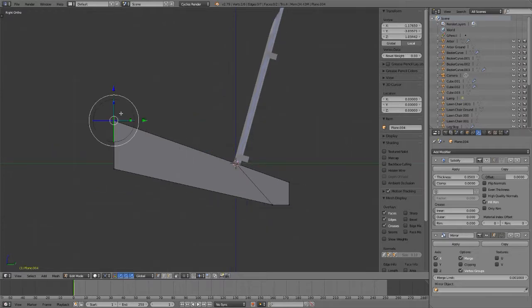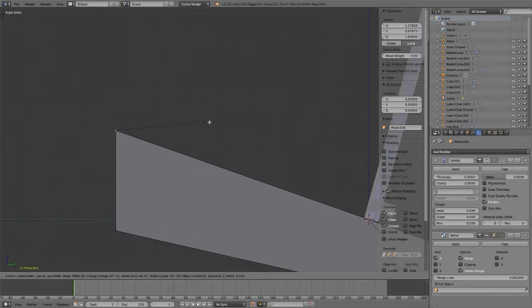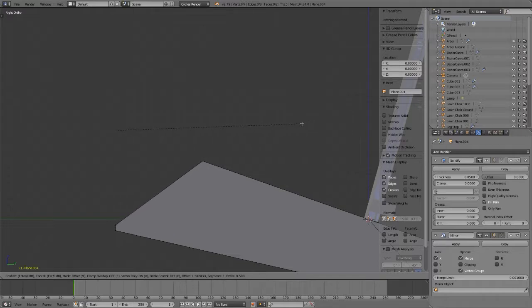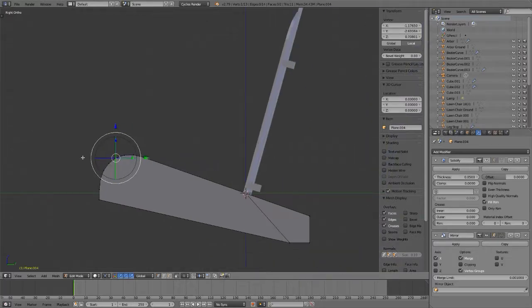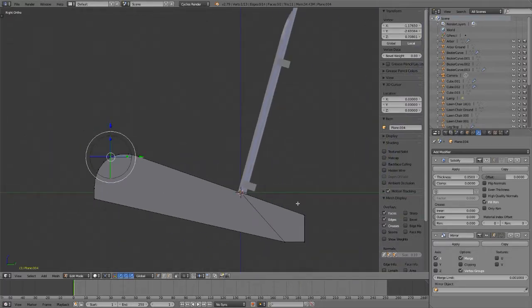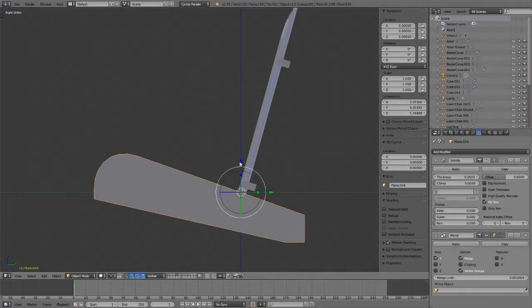I'm going to take this and now Shift Control B. I'm going to bevel it with 5 segments, moving my mouse to make those segments, maybe I'll go 7. So it looks like that final vertex on the bottom left corner there is a part of this group. It looked like this guy and this guy are equidistant, so they're all equidistant. This whole thing I'm going to raise in object mode.